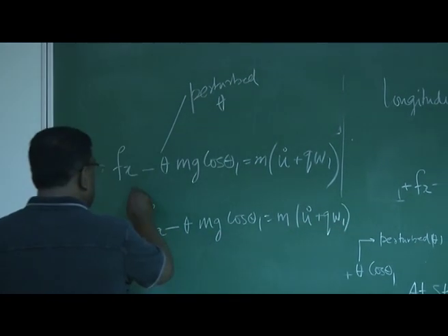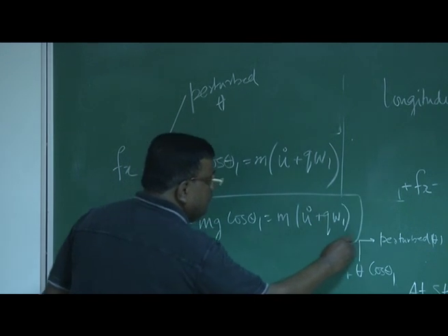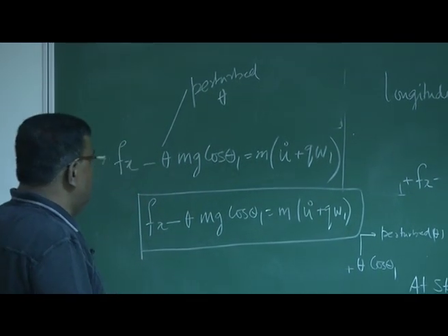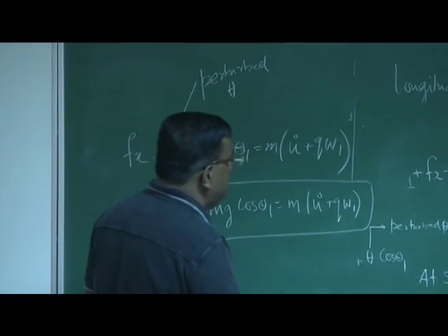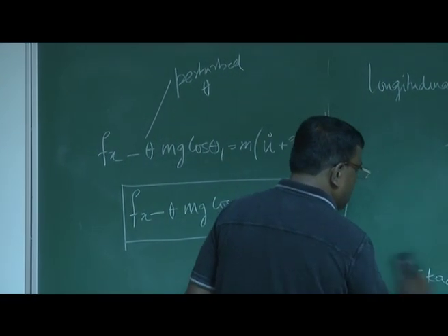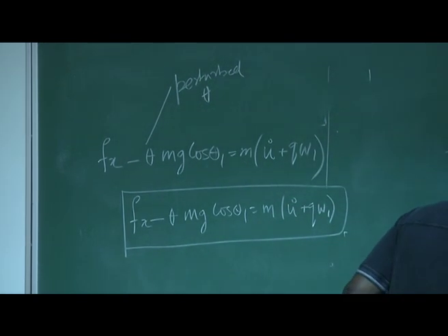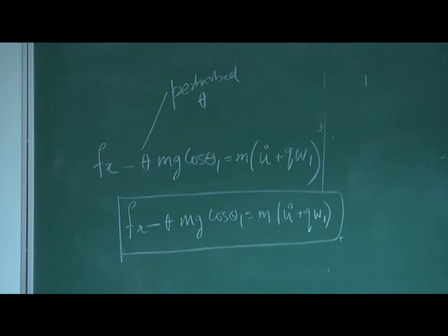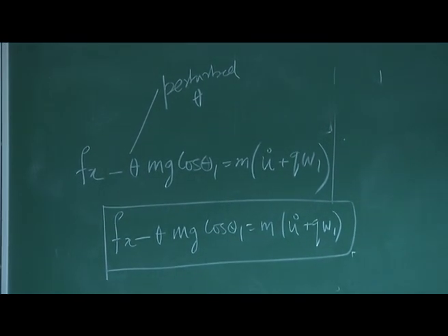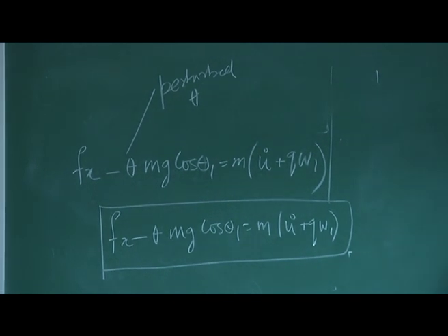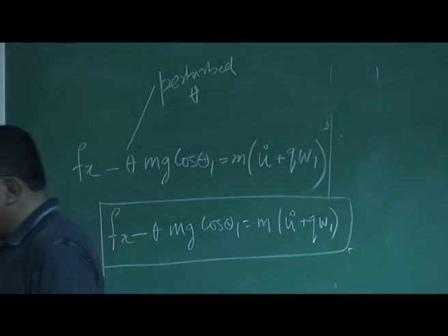So this is one equation of motion which is written along the x direction, body fixed x direction. We will do some more modification or more assumption so that things look pretty simple. But for all of you, I must tell you, you have to do it once and then forget it. Then you use the final equation and try to understand the physical meaning of all these terms.